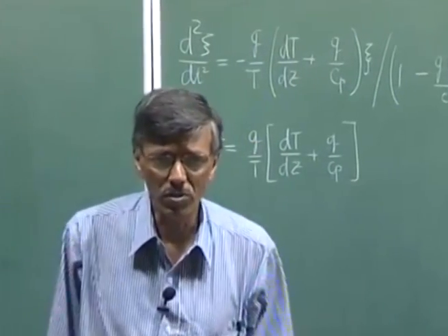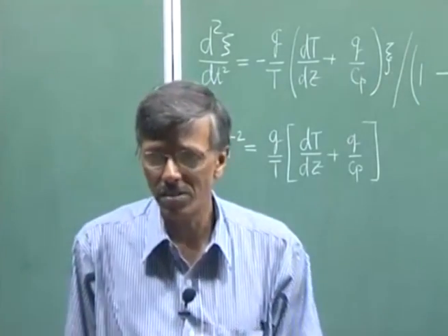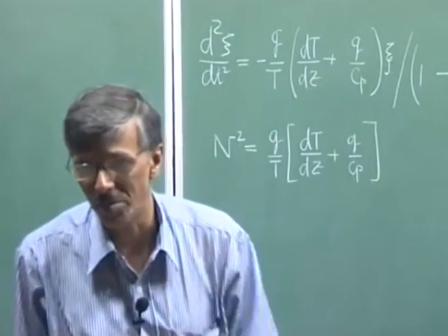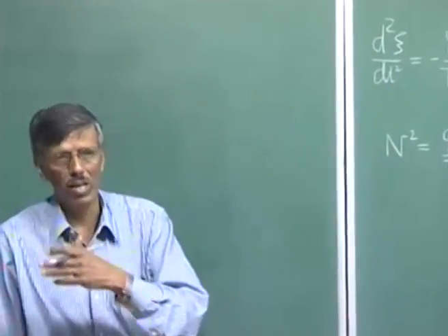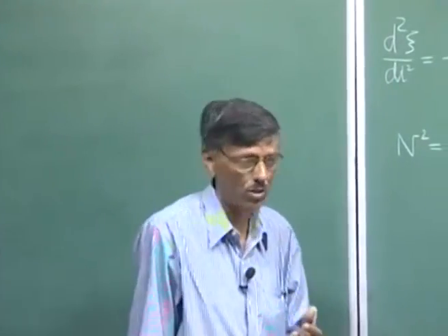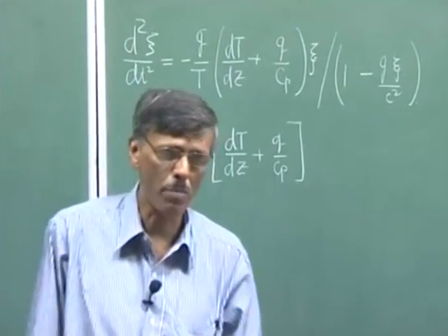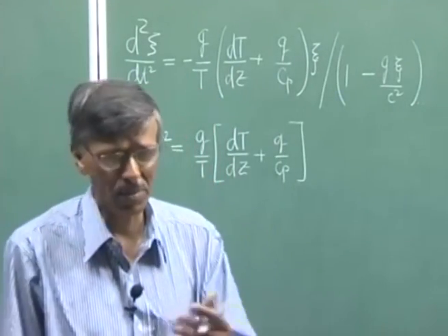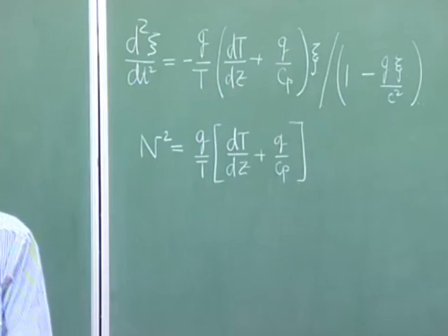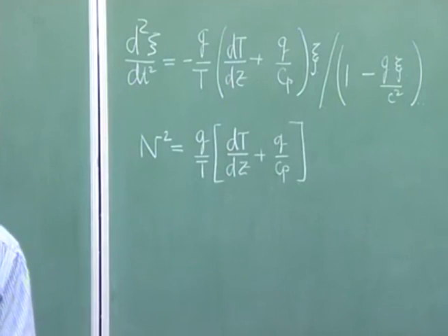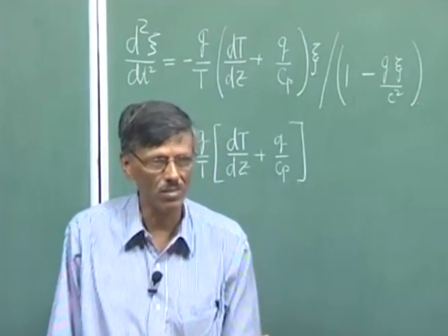We also know what is called the International Standard Atmosphere, or ISA, which gives us a statistical distribution of temperature variation, and which says that dT/dz is a negative quantity, falling at a rate which is called the lapse rate. Okay. The usual standard taken for the tropics as well as the temperate latitudes is that dT/dz works out to something like 6.5 Kelvin per kilometer. Although we must emphasize that that is statistical information.